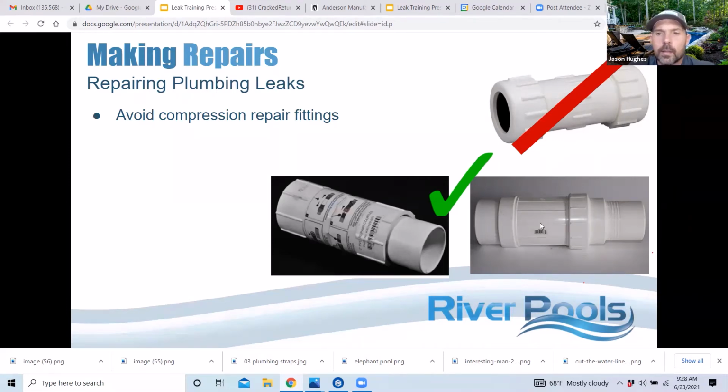The one on the right, the 2-inch pipe or whatever size pipe, inserts into that right here, just like a fitting. On this side, you glue a coupling and then this extends, and there are two O-rings inside that apparatus. You fit the one side on, then slide the other coupling on, and it gives you a variable length you can work with, and it holds up to some ridiculous 750 psi.